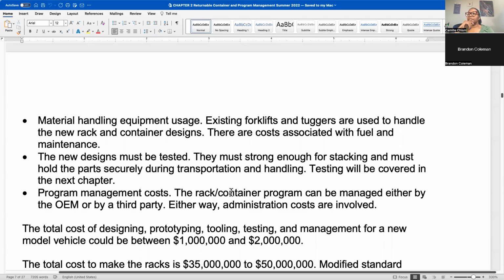Mentioned about the testing. So an example would be with the racks, where the racks need to be tested to make sure that they don't break off if someone drags them across the top of the door. Also, if you have a rack that is going to go by rail, are they going to be able to withstand the rail vibration or truck vibration? And not just for racks, all the designs, you have to do transport testing on the packaging. If it's new, if you find that the product is vulnerable and needs to be protected by packaging, those are some of the things that you do.